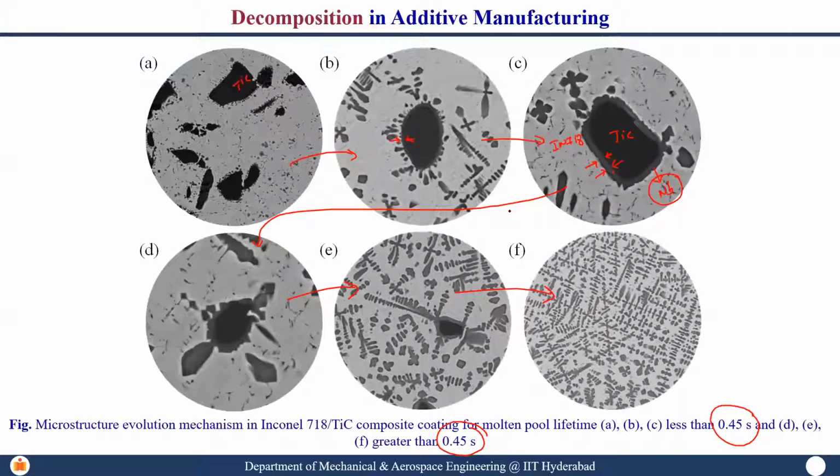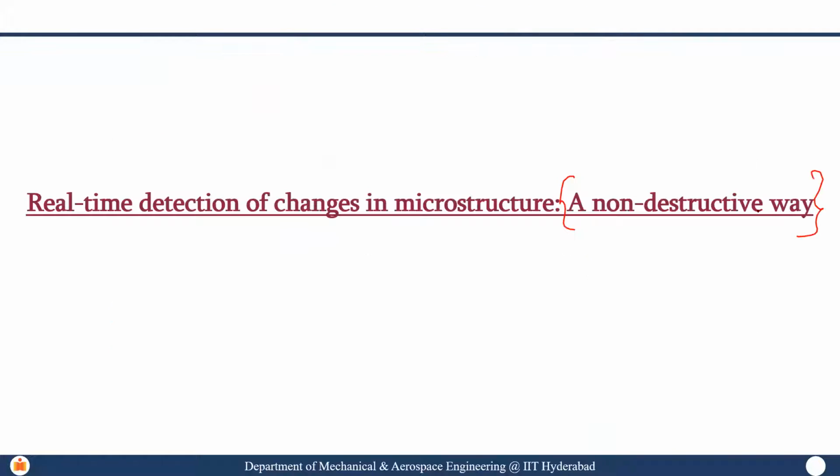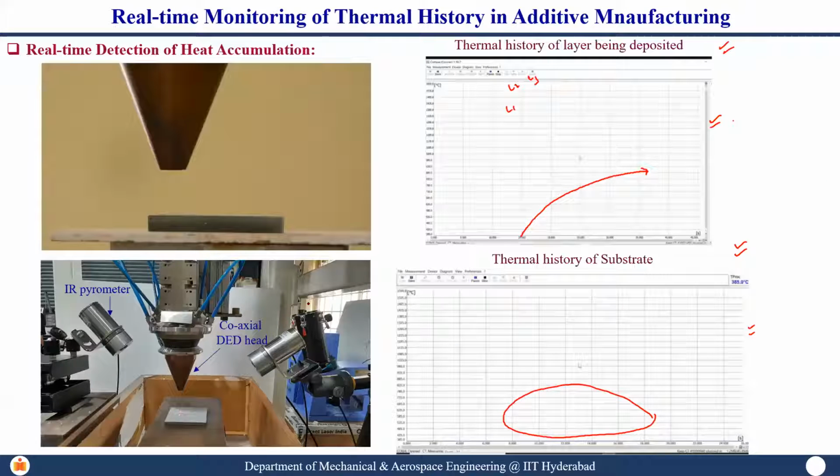And then another question from Prathivi Rajan. He asked about how to get the pyrometer to focus exactly at the melt pool. So this pyrometer has optics. It is a detector, and from this particular molten pool, your IR radiation is coming like this. But how do you focus it onto the detector? What we do is keep a plano convex lens. Now the distance from this point to this point should be the focal length of the lens.